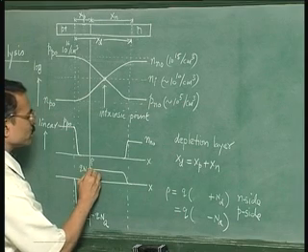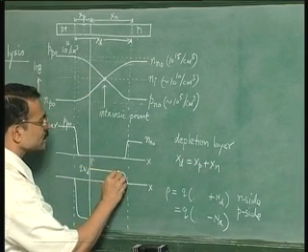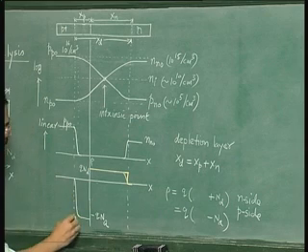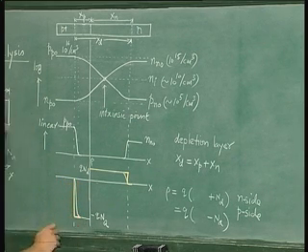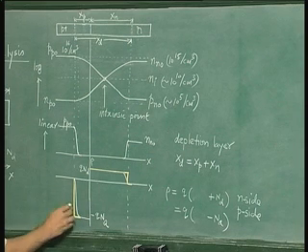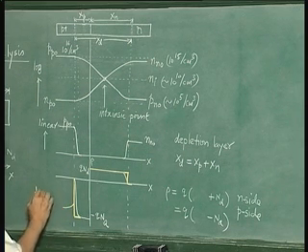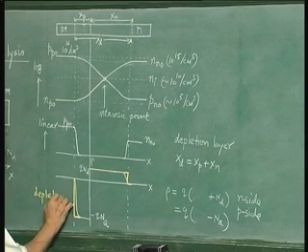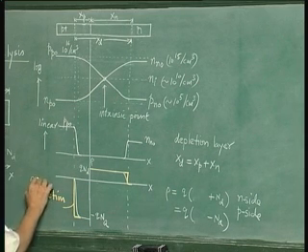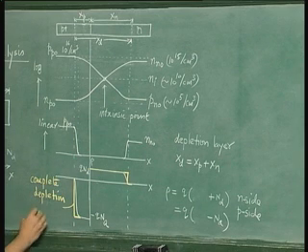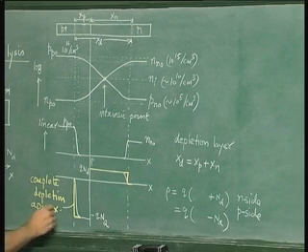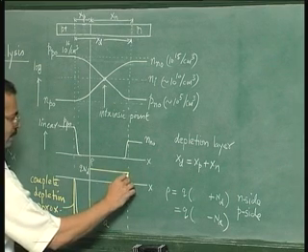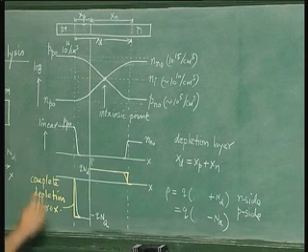So in this approximation your space charge will be shown like this and like this on this other side. Okay, so this is the so called depletion approximation, complete depletion. The same applies to this line. This is done to simplify the analysis.